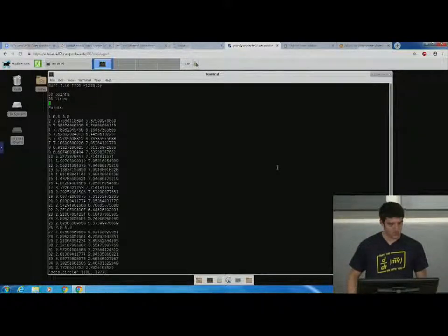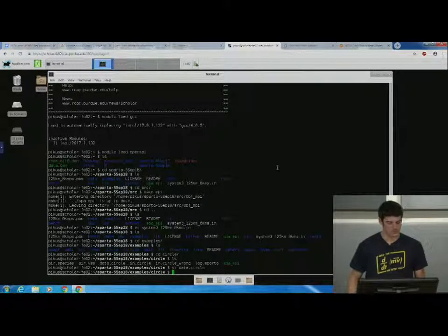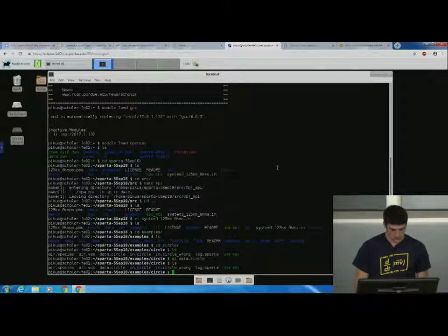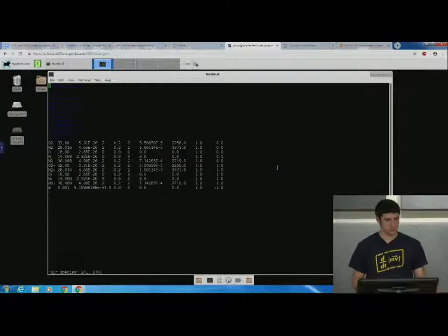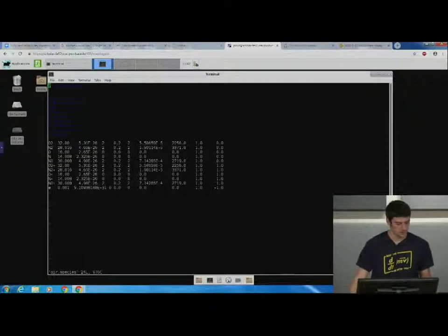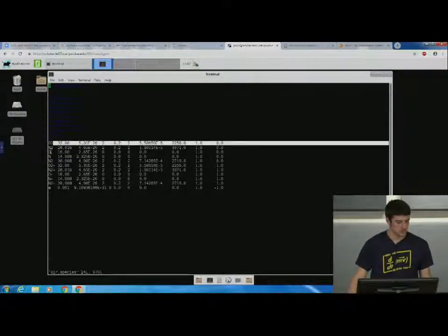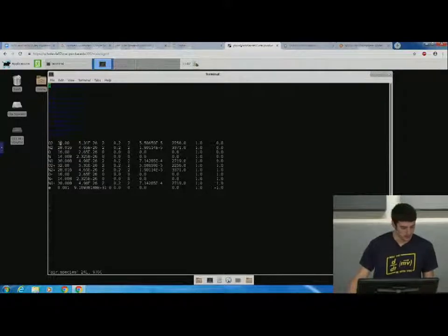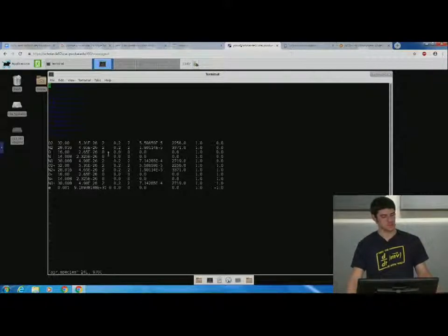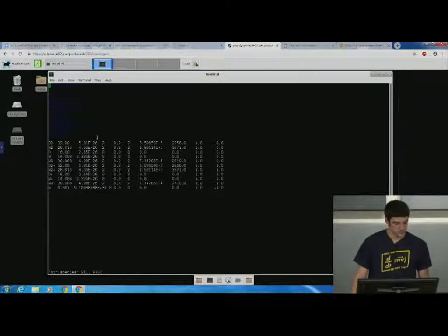I'll hopefully have time to show you how to create some of these surfaces. But one thing, if you remember the species file air.species that we referenced earlier, that's all shown here. So here I have the names of all these species, O2, N2, so on. The molecular weight, the molar mass, then rotational degree of freedom, and you have all these things here. Basically, unless you want to add new species, you can just stick with what's in this file. If you want to add new species, then you have to add each one of these.